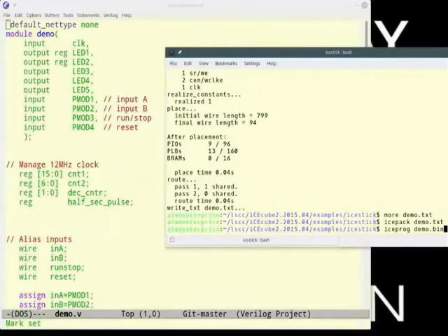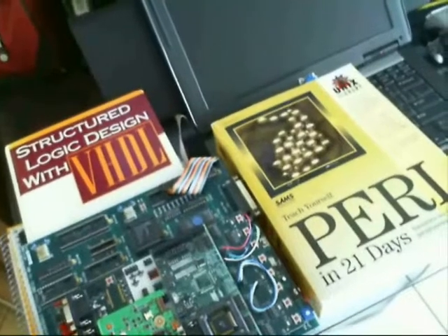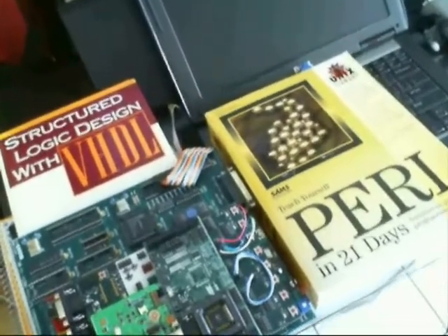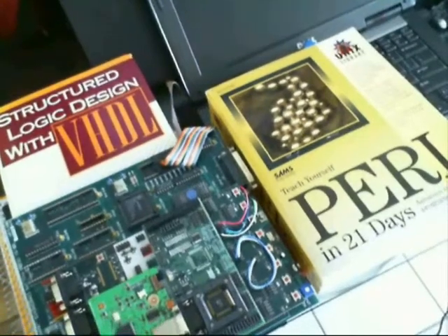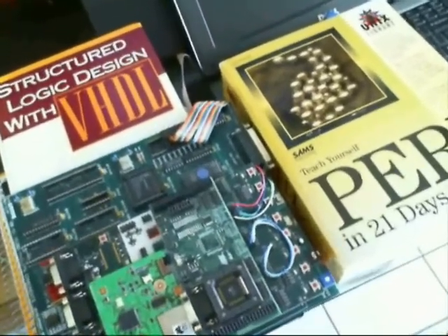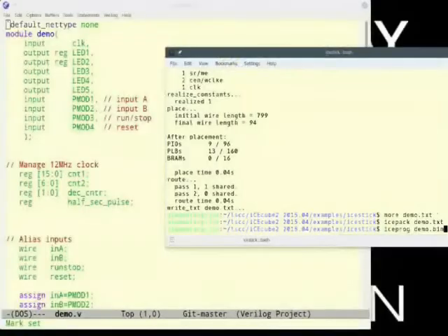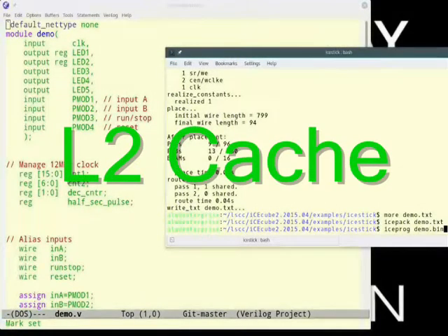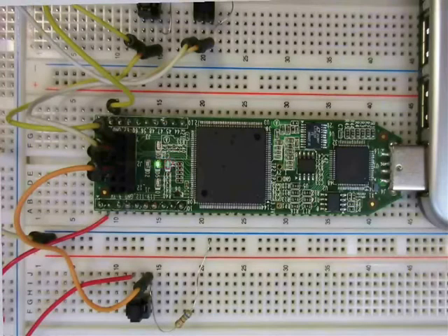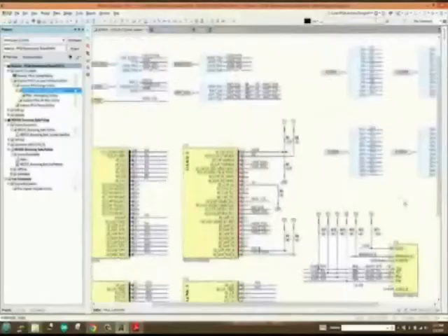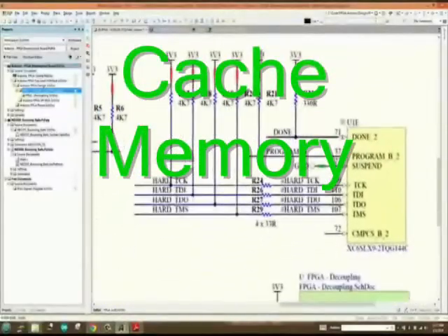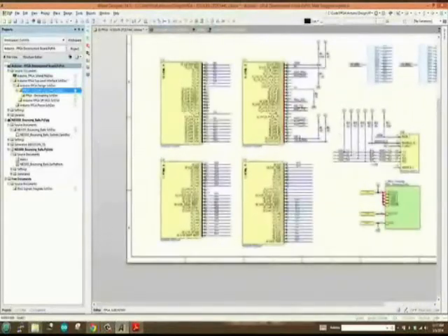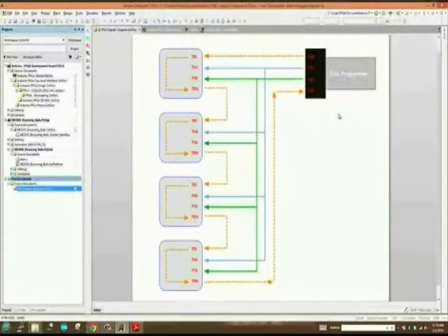In this design, the memory hierarchy is well defined. The high speed of hits and misses is important. For instance, hit time is the time to access the upper level of the memory hierarchy, which includes the time to determine whether the access is a hit or a miss. Miss penalty is the time to replace a block in the upper level with the corresponding block from the lower level, plus the time to deliver this block to the requesting device, normally the CPU.